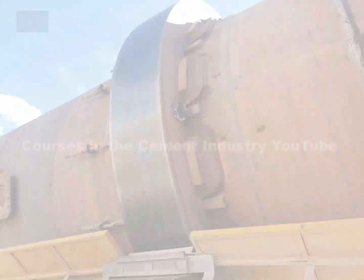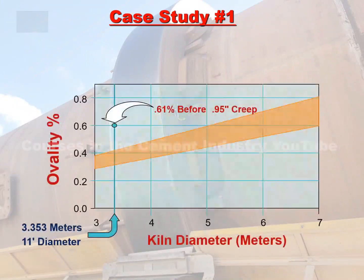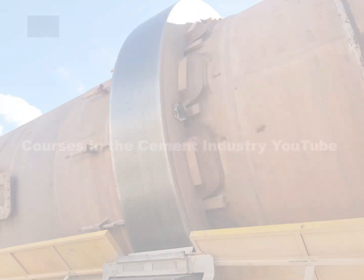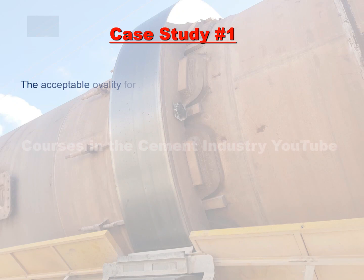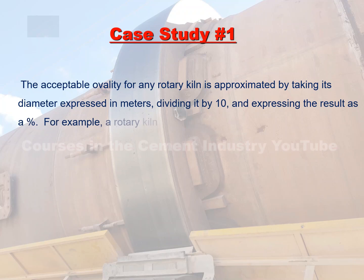We follow together the analysis of Case Study 1. In this figure, acceptable ovality range. In the previous slide, the acceptable ovality for any rotary kiln is approximated by taking its diameter expressed in meters, dividing it by 10, and expressing the result as a %.